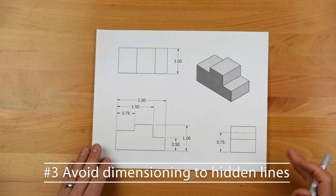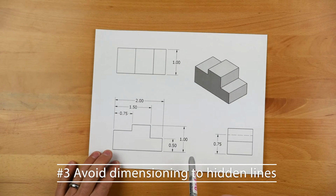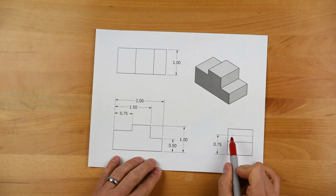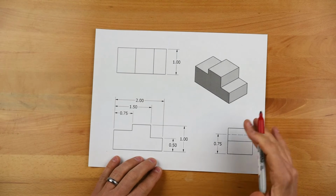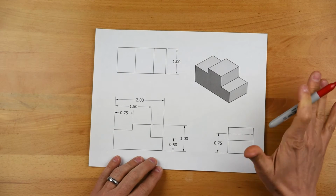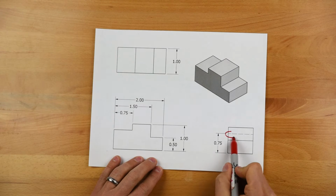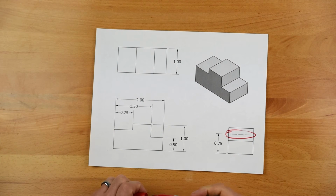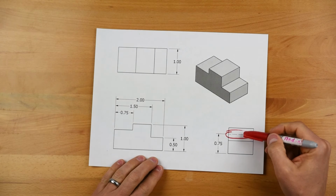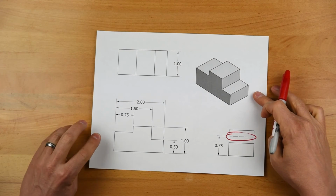All right, here's an example here. This is just a simple one. We have a lot of our dimensions here. It all looks pretty good. But one thing you'll notice is that we're dimensioning to a hidden line over here. Now, of course, that kind of violates our last guideline on dimensioning where the contour is. But the next guideline that I want to talk about is trying to avoid dimensioning to hidden lines. We really want to try to avoid that as much as possible. If we're going to dimension to a hidden line, you may want to consider using a section view or some other way of showing that.